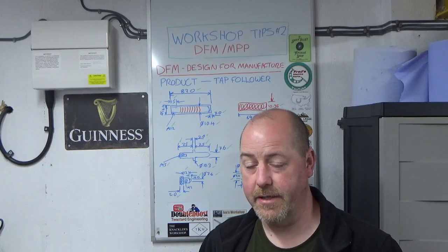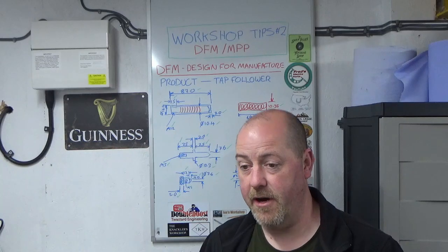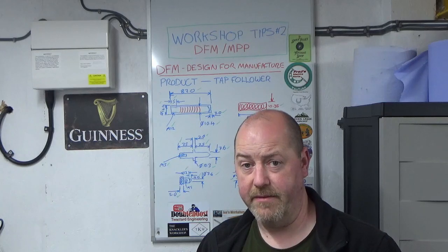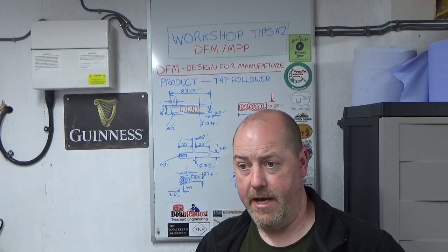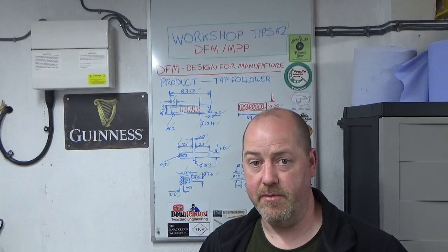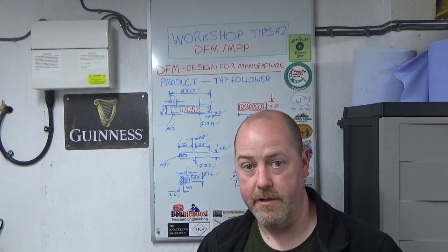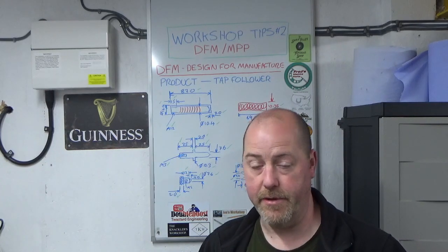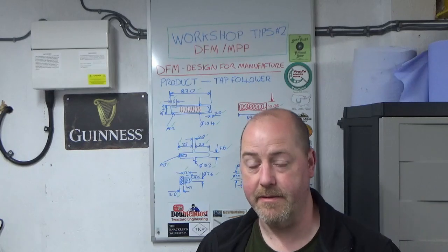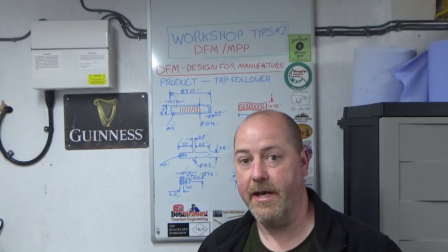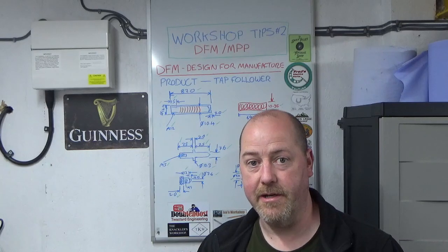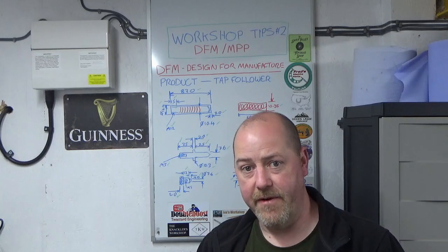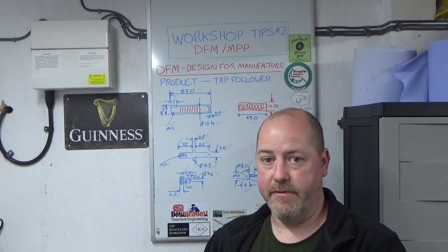So you've got a designer working in absolute isolation, making stuff, and I've been several times in my career on the receiving end of that, where we've been given a drawing to make something, and it's absolutely physically impossible to get tooling anywhere near the features that have been designed into the product, and that's just through lack of knowledge of the guys designing it. They know they want a hole in somewhere and a pipe needs to go into it, but they've got no idea how you're actually going to get that hole in there, but it's the right place in the design space for the hole to be. So that's DFM in a nutshell, at a very, very high level and a sort of a worked example.